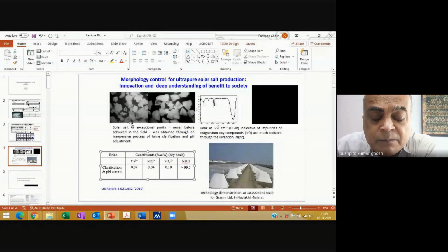And when I say alum, I'm talking about 10 to 20 ppm. You're not talking about dumping huge amounts of this stuff. And you know that alum is very effective for flocculation because of the Schulze-Hardy law, where it goes and sits on the surfaces, and that interaction energy almost goes as the cube of the charge. So if you've got a +3 charge, it will become 27 times more effective than something which is +1 charge.